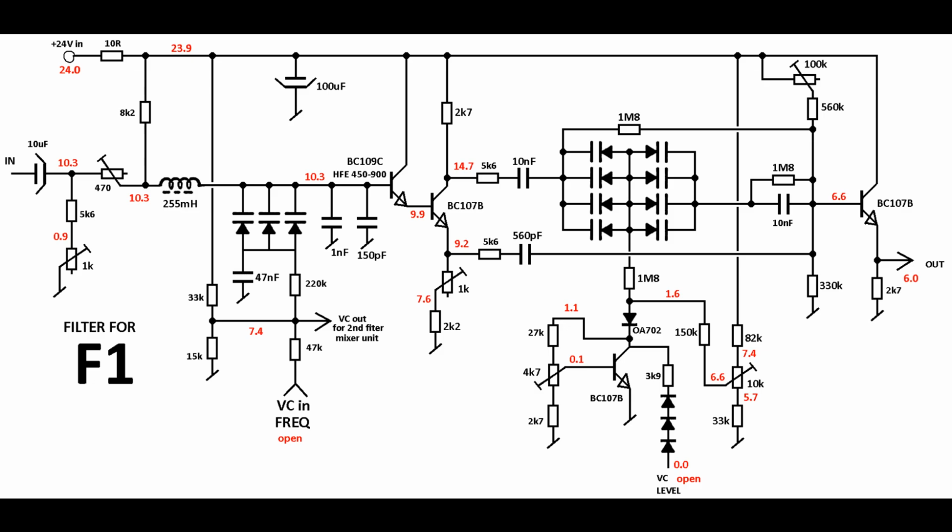And obviously you can see if this is not mounted on this PCB, any kind of AC noise on the 24 volt supply bus will obviously affect this circuit. It's going to go directly to the audio output, and so that was some of the reasons for the weird noise and hum and funny sounds, and that has been cured simply by adding those local filters to all the units.